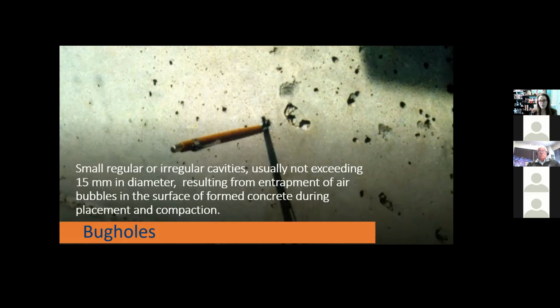There's two types of air. You've got your entrained air that's going to hopefully be thoroughly mixed and homogeneous in that mixture and properly spaced apart. And then we have what we call entrapped air, that's your natural air from folding, that is going to need to be consolidated out. And this is what you're trying to do here.